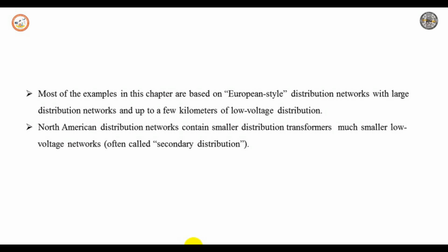The requirements are deemed to be satisfied for a given supply if the voltage drop between the origin of the installation and the fixed current-using equipment does not exceed 5% of the normal supply voltage. A greater voltage drop may be accepted for motors during the starting period, and for other equipment with high rush currents. It is to be verified that voltage variations are within the specified limits of the relevant Indian standard, or, in the absence of an Indian standard, in accordance with the manufacturer's recommendations.